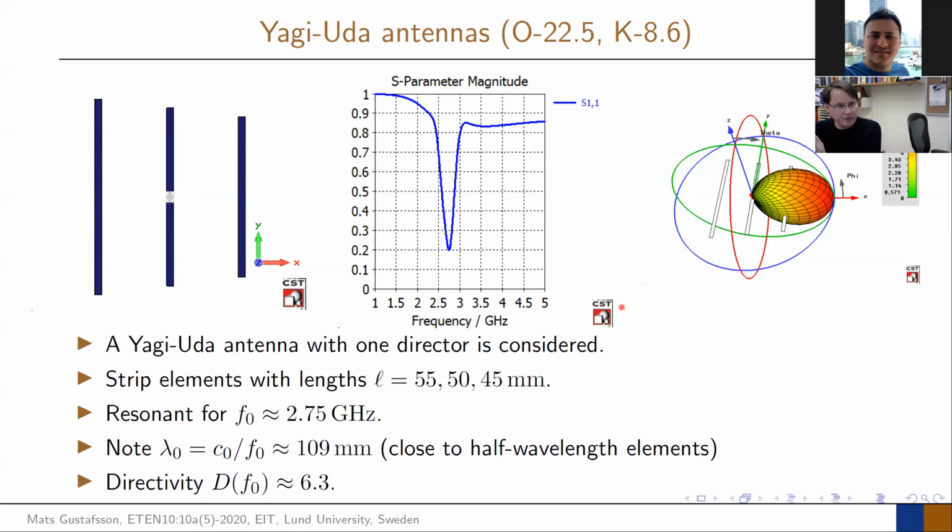The radiation pattern is really this polar type plot, a spherical coordinate system. You can see it has an x-axis here, which is theta equal to 0. Then you have the spherical coordinates, where in some ways the distance from the center says what the directivity is, while the antenna is plotted in its own coordinate system.